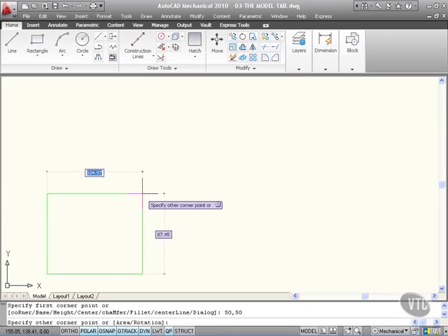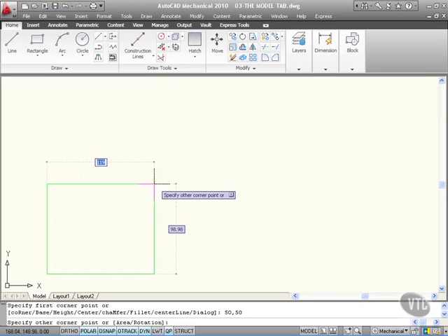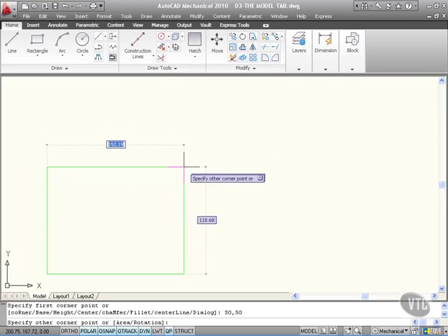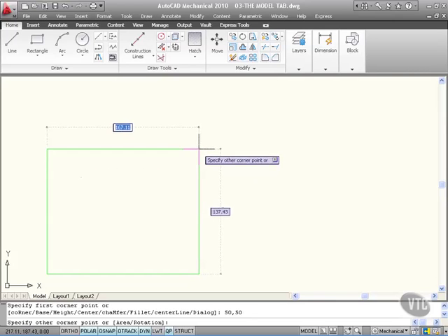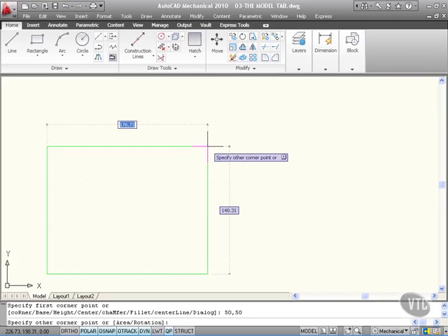Now, as I come away, this is what I love about dynamic input on AutoCAD. Dynamic input has been around since AutoCAD 2006, and as you can see, as I move the rectangle, it gives me the sizes of my rectangle. So there's my side. So I want that top side, see the blue there? As I move the horizontal distance, I want to be 250. So I'll type in 250.